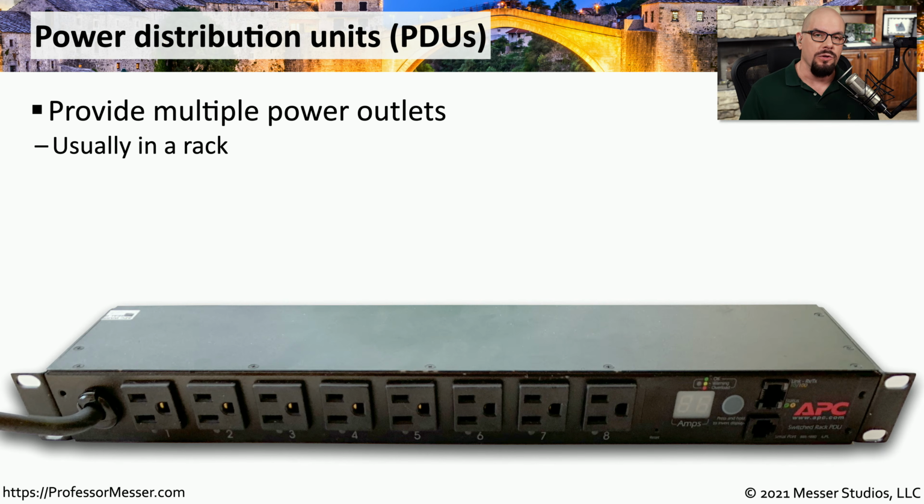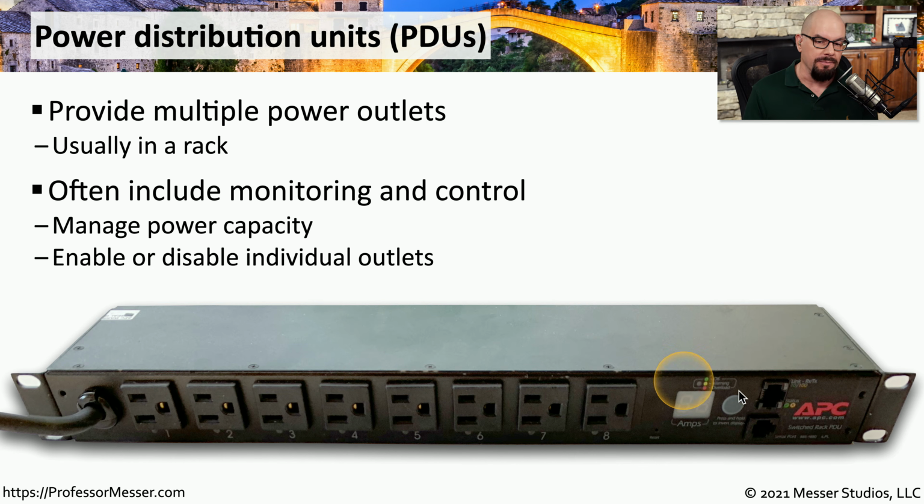In the rack itself, you need to have some way to connect all of your servers and components to a power source, and this is usually done by using a power distribution unit, or a PDU. This is a PDU that I use in my studio. This one is a small one that is rack mountable. It has 8 outlets, and I'm able to access this device across the network to be able to turn on or turn off any of these outlets. Many PDUs provide monitoring functions so you can see exactly how much power you're using, and PDUs like this one also have SNMP availability so you can manage it from a central workstation.